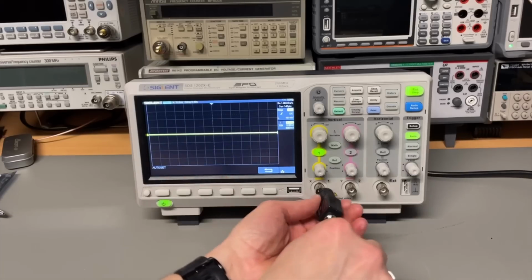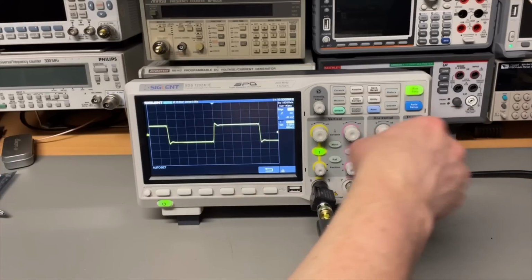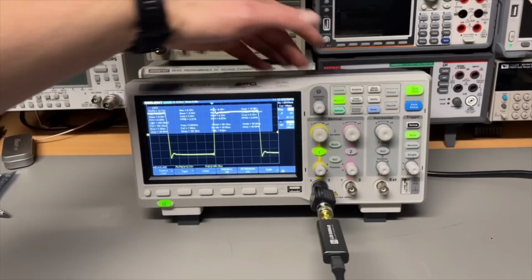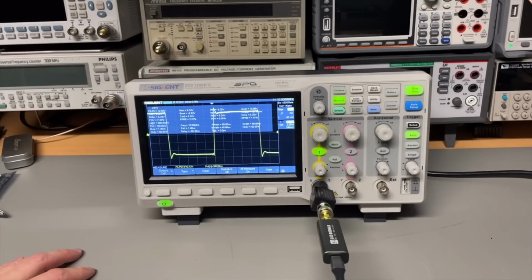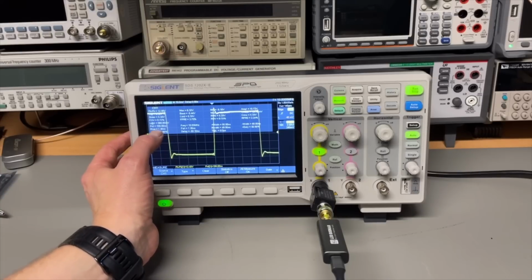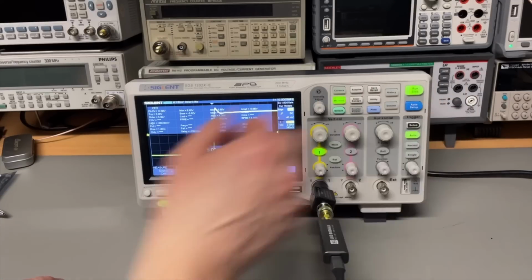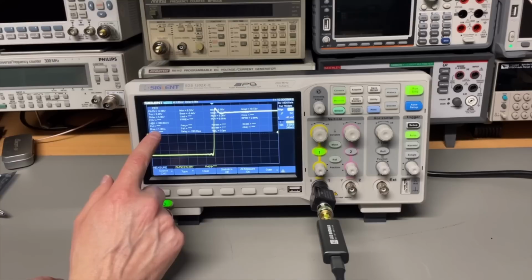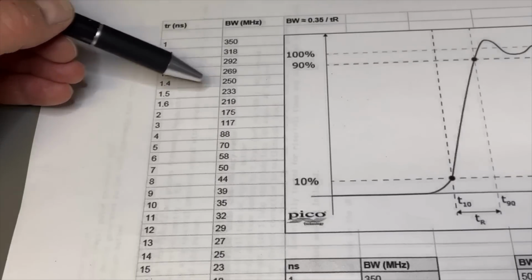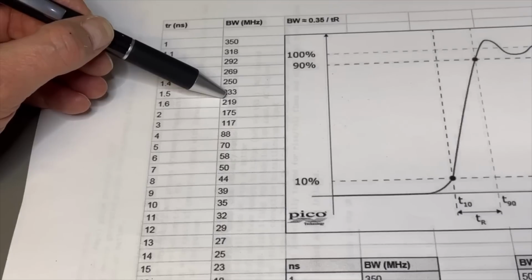And the more modern is a lot easier because they have the measure menu. I can maybe zoom in a little bit more. Then we go to the measure menu, and we can see here the rise time. It's a bit full, but here we have the rise time. It is jumping between 1.3 and 1.5. Maybe it becomes more stable. Yeah, now it's more stable. It says, yeah, still 1.3, 1.5. Yes, well, if we see 1.5, we are around the 230 megahertz, and that's about correct because the oscilloscope is